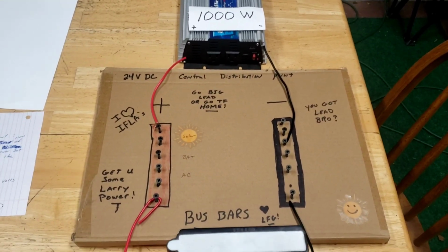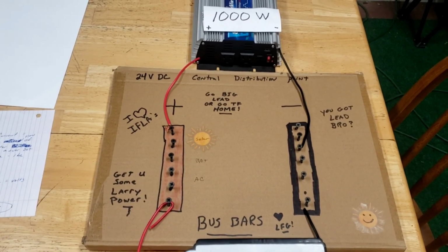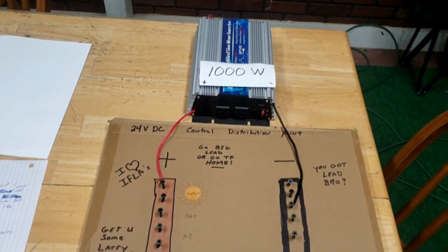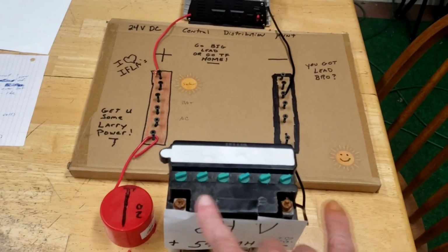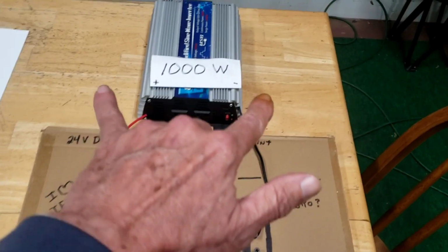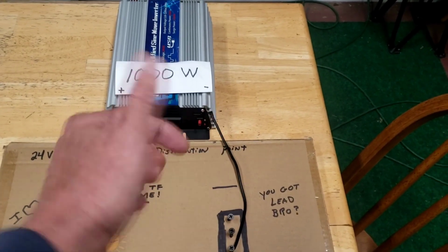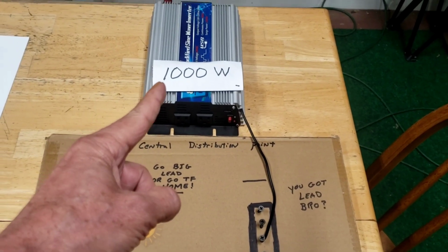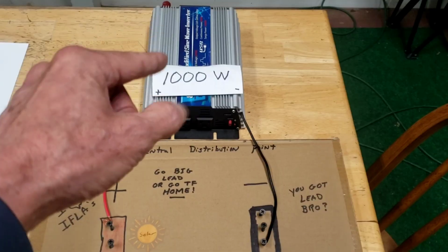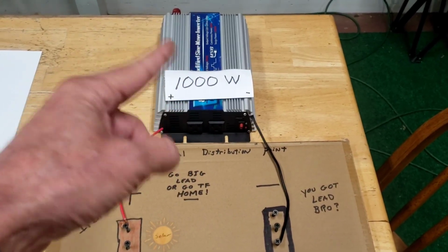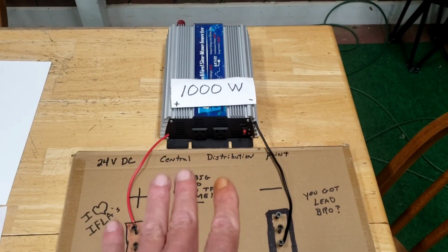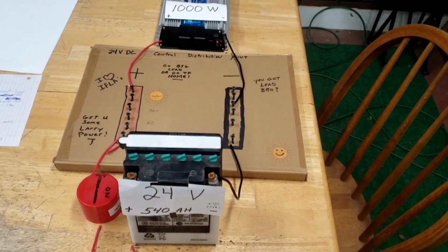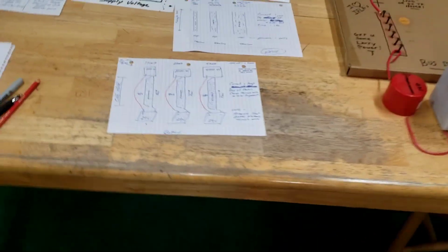And to take this a step farther, if you come out to your solar system and it's dead, this inverter's off and the switch is on, the first thing you'd do is troubleshoot it. You would check your voltage here, check your voltage here, and if there's volts sitting here, if your garden hose is sitting here and it's not spraying when this should be spraying, then that tells you that something in there broke the connection. Something in there stopped the flow of the water. So a little quick troubleshooting on top of our lesson here. When you understand the flow of it all, that makes it kind of easy. So just throw that in there quick.